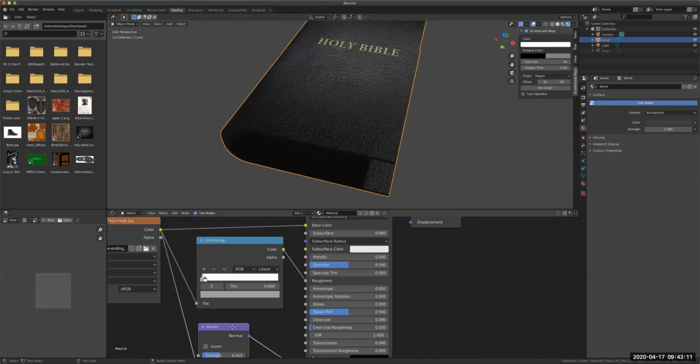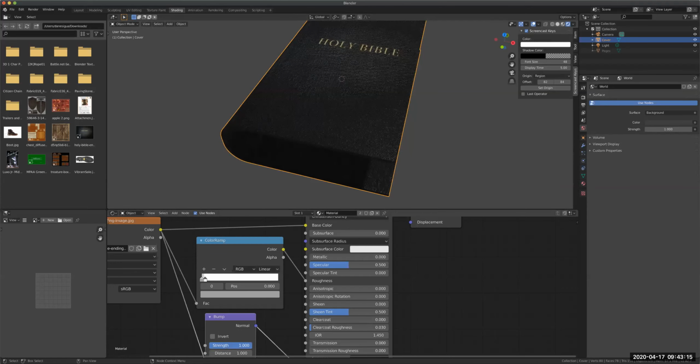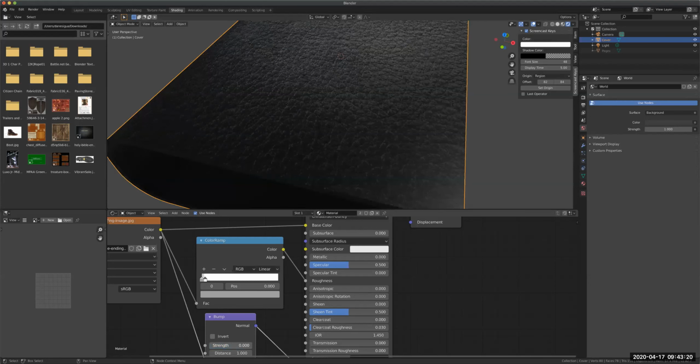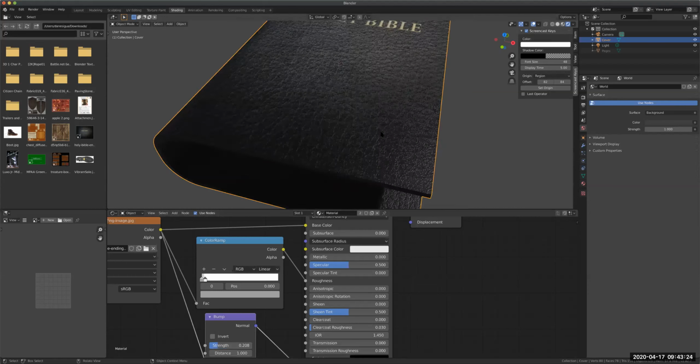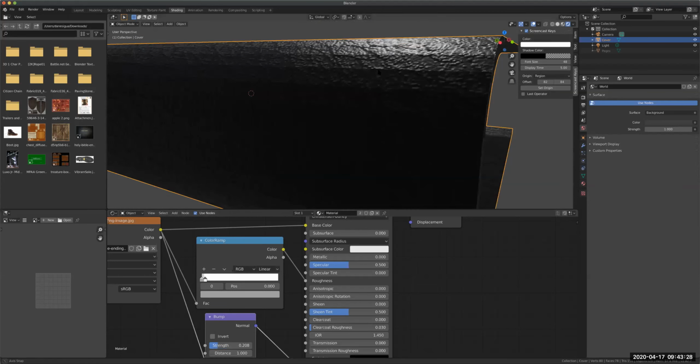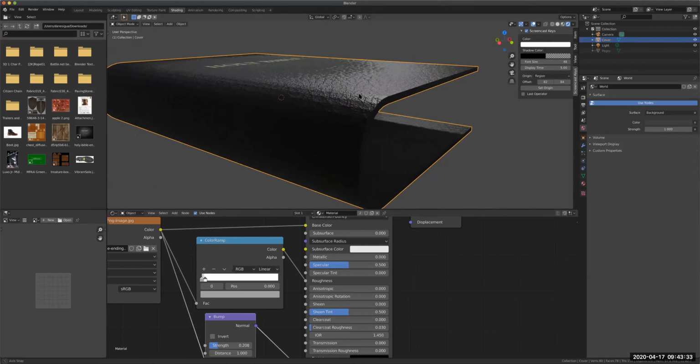Let's take a look at our bump. Just drag that to 0.4. That's for starters. So let's see the original one, very coarse and rough, all the way to 1, 0, no bump at all. So I'm just gonna move that to 0.2 maybe. That's probably good enough right there. Okay, but you see the faceted lines that we added in that bump section right there.